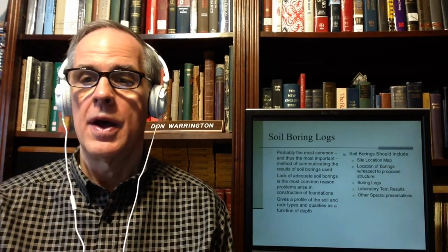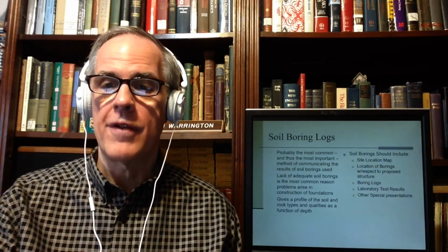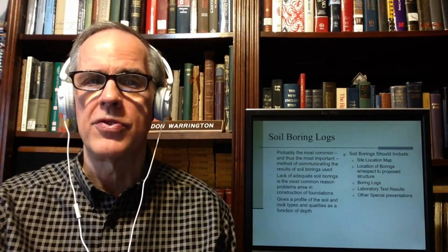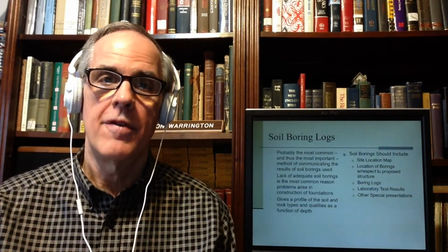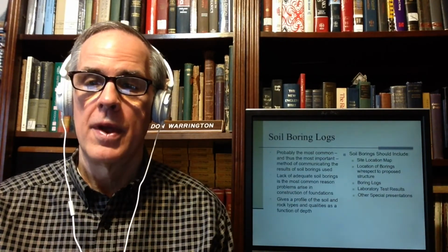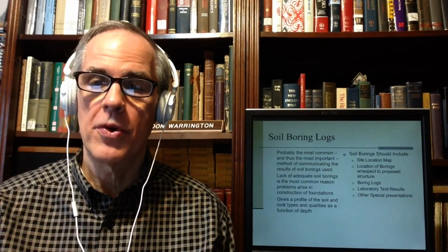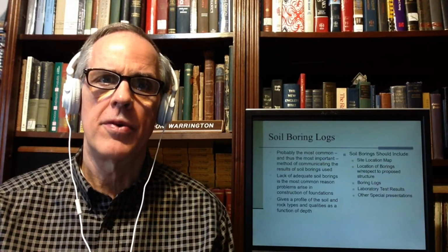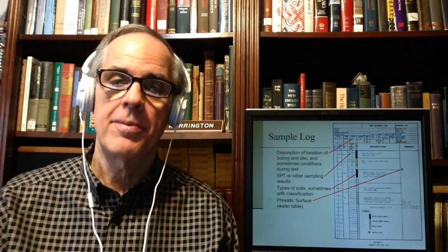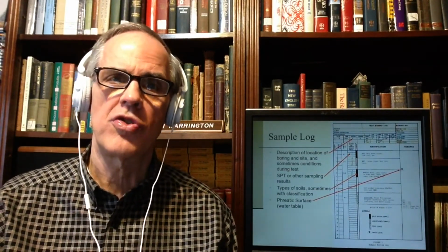So soil boring documentation should include quite a few things. Laboratory test results, I see those very commonly with soil boring logs. The boring logs themselves, the site location map, and soil profiles as well. We'll talk about that in a minute. This is a sample boring log. This is kind of old. It has a description, location of the boring and the site. Sometimes the conditions during the test are noted, and usually the site plan will show the locations of the borings.